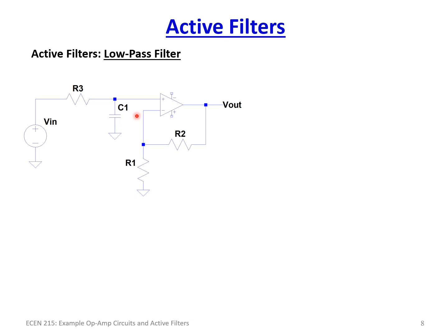If you go back to the frequency response lecture and use a low pass filter out of there, it can complicate things, because as you put a different load resistor here, you're going to change the effective cutoff frequency of the filter. In this case, you would change the cutoff frequency and cause it to shift. Well, that is not the goal. The goal is to simply have a resistor and a capacitor that set our frequency, and no matter what load I stick out here on V out, it is consistent.